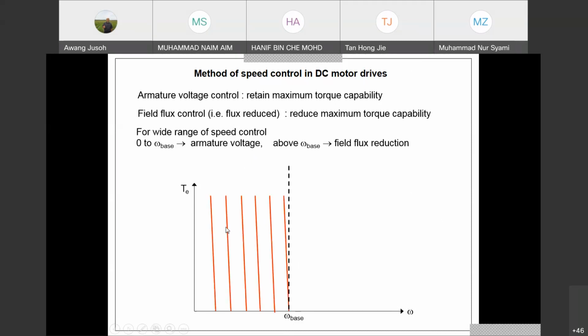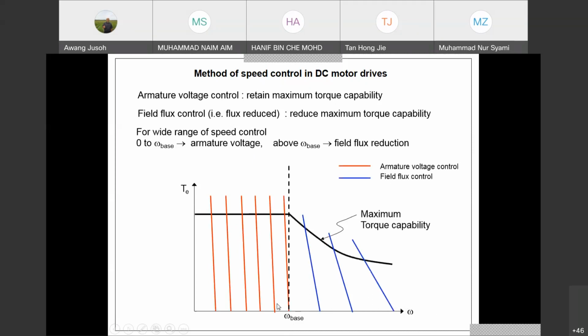That's why I told you just now, when you use the torque speed profile, the voltage plot will be vertical. It's not horizontal anymore, it's vertical, because you just reverse the axes. So this is your low voltage, and this is speed. The intersection between torque and this represents the voltage: voltage 1, voltage 2, voltage 3, voltage 4, voltage 5, rated voltage.